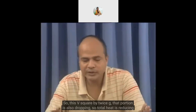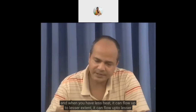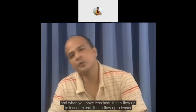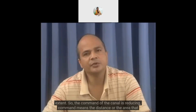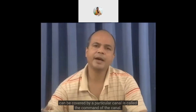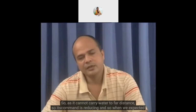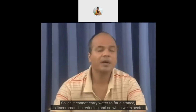So total head is reducing. And when you have less head, it can flow up to a lesser extent. So the command of the canal is reducing. Command means the distance or the area that can be covered by a particular canal is called the command area of the canal. So as it cannot carry water to far distance, its command is reducing.